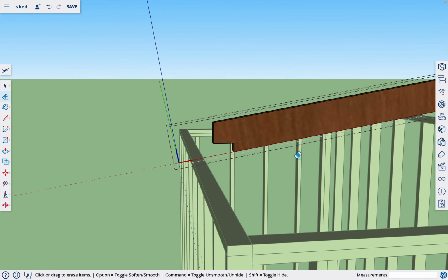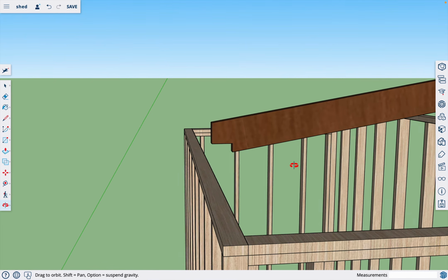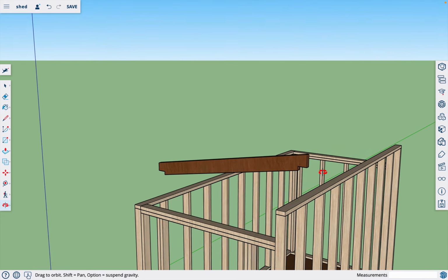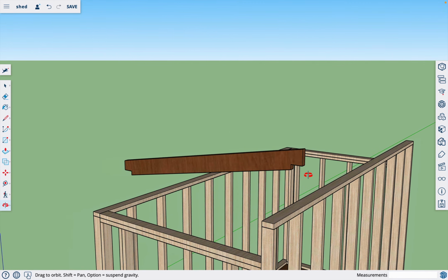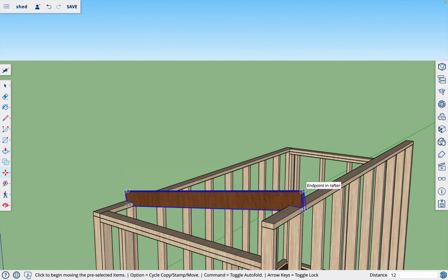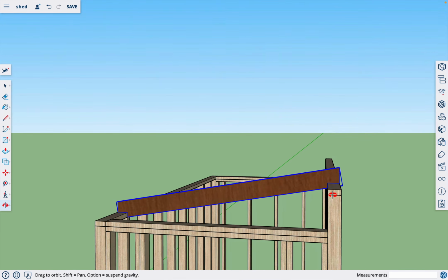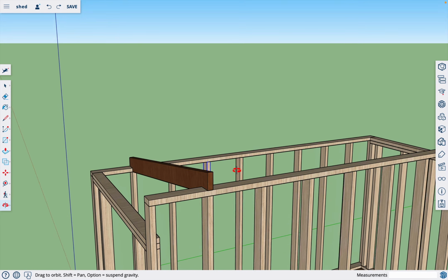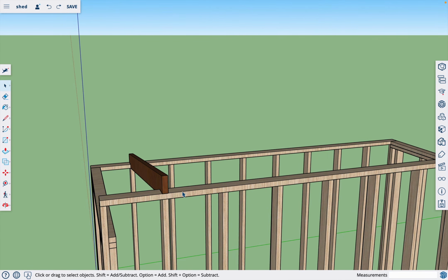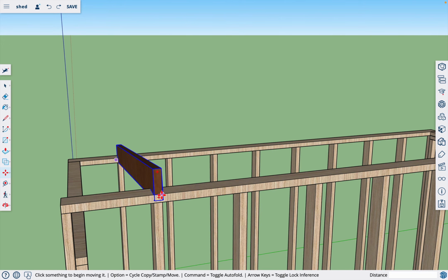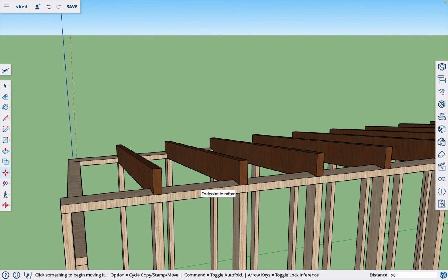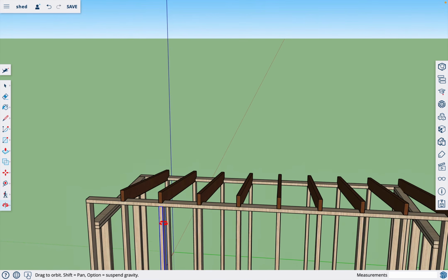And so now, let's see, rotate with the orbit tool, which is O. Now if we pull this down 12 inches, it should sit perfectly flush on our framing there. 12, enter. So there it is. Okay, so now we're going to copy this across the project here by clicking M, Option, drag this over 16 inches, enter, times 8.